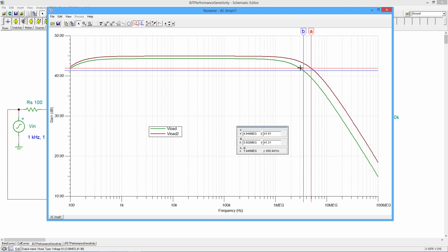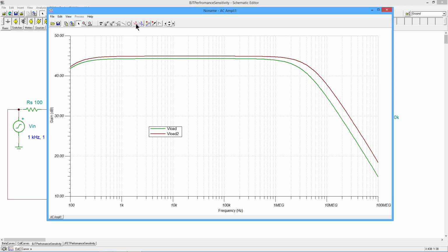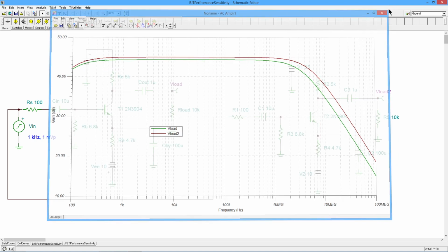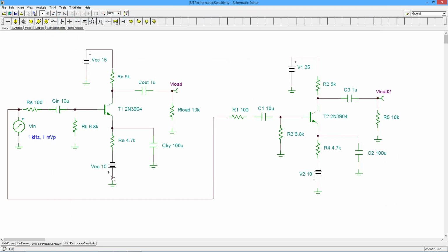That's 3.5 megahertz for the first one, the green one here on the bottom, and the maroon one, which is the higher bias version, again, about 5 megahertz. So that's a pretty sizable change in terms of the frequency response. Granted, the gain change isn't that much, but the frequency response change at the top end is sizable, going from 3.5 megahertz to 5 megahertz. All right? Okie doke. Now, same thing is true if we were to look at a JFET.